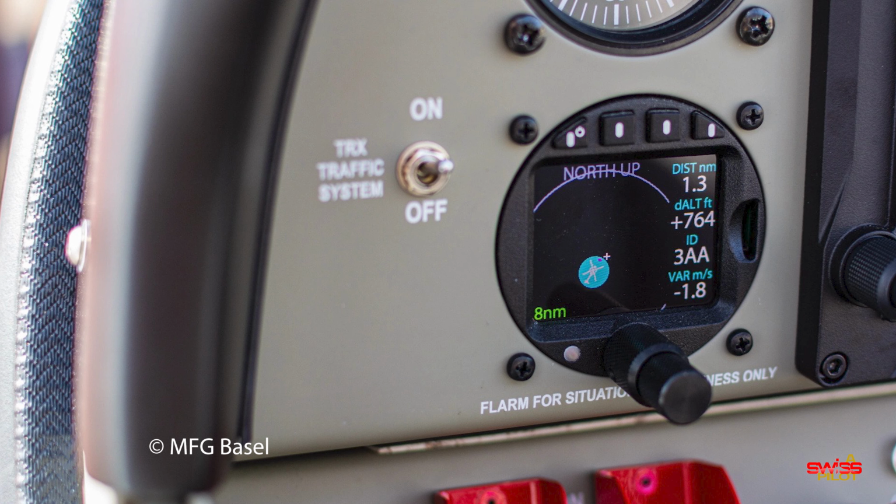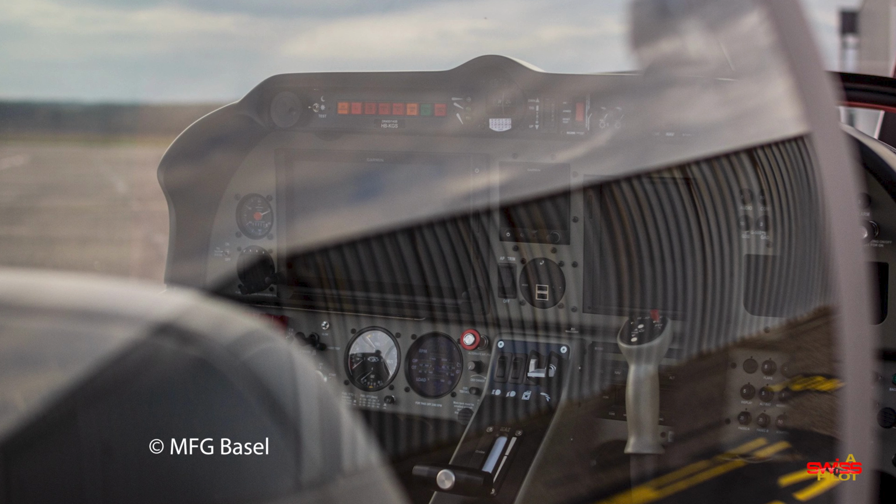If you are an expert and you find some information is missing or maybe even wrong, please let me know. If you actually decide to upgrade a plane in your flying club, or you have a flight school and you want to upgrade your fleet there, or you own a plane yourself, make sure to talk to an avionic expert who will then also be able to look at the aircraft individually and check how it can integrate into the existing avionics. What I've heard, in some cases it might actually be better to use a dedicated traffic display instead of an existing MFD or a navigator or an iPad display, to also show traffic which is presented with range information only.